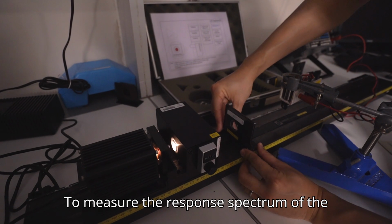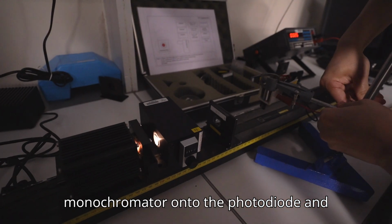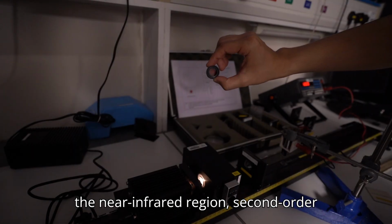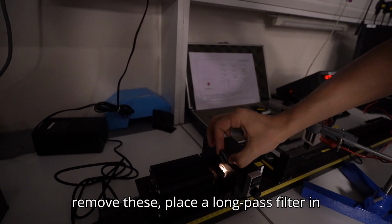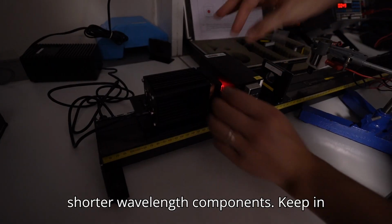To measure the response spectrum of the photodiode, focus the light from the monochromator onto the photodiode and record the signal with a multimeter. In the near-infrared region, second-order diffraction can introduce artifacts. To remove these, place a long-pass filter in front of the monochromator to block the shorter wavelength components.